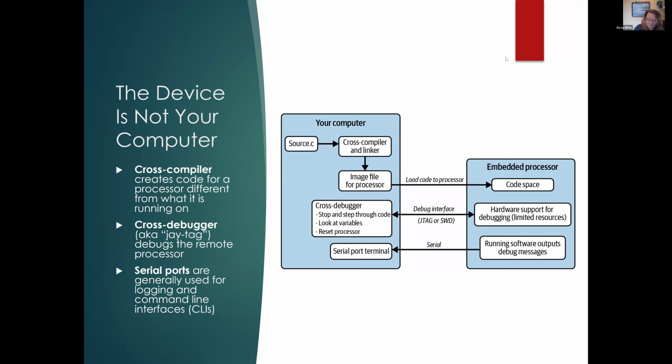This can change the timing of the code, leading to annoying bugs that occur when you are or maybe aren't debugging. And internal registers take up space. They take up resources. So often there are only a limited number of breakpoints. Frequently, there are only 2 hardware breakpoints. What can you do with 2 breakpoints? Quite a lot, actually. But it can make debugging the software feel like playing Tetris at level 10.